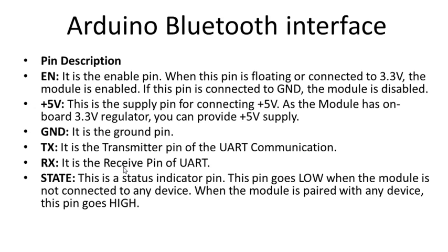TX and RX are used for transmitting and receiving data from the microcontroller. When Bluetooth sends data, the microcontroller will receive it with the help of the TX and RX pins. The TX pin is used for transmission and the RX pin for receiving data from the Bluetooth module. How we can use it and interface it for our application is very interesting.